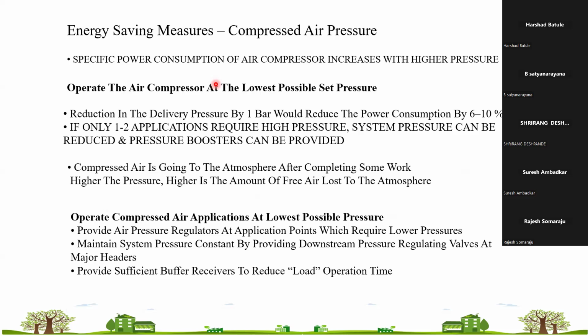Yes, this is one of the energy saving methodologies where bigger size compressors are used, 90 kilowatt or 100 kilowatt compressors. Hot water can be generated through the compressors. Majorly in a water cooled compressor, your intercoolers and aftercoolers are connected to your cooling water circuit. And if we allow heat recovery from that, we directly connect it to a heat exchanger, and then hot water can be generated through this circuit.